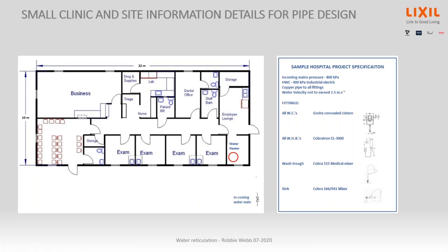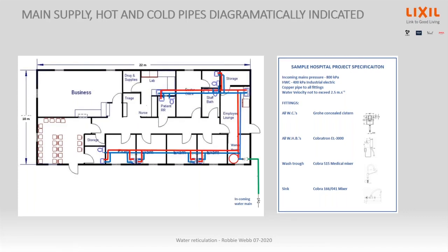So do the exact same thing. We size up the layout where we're going to put the piping. So let's say here we're running it in the ceiling and we're going to drop down. It's diagrammatic on the drawing anyway. So in real life, doing the plumbing, you're going to find the right place for it. But to get to the size, we're going to lay it out on the plan like that.